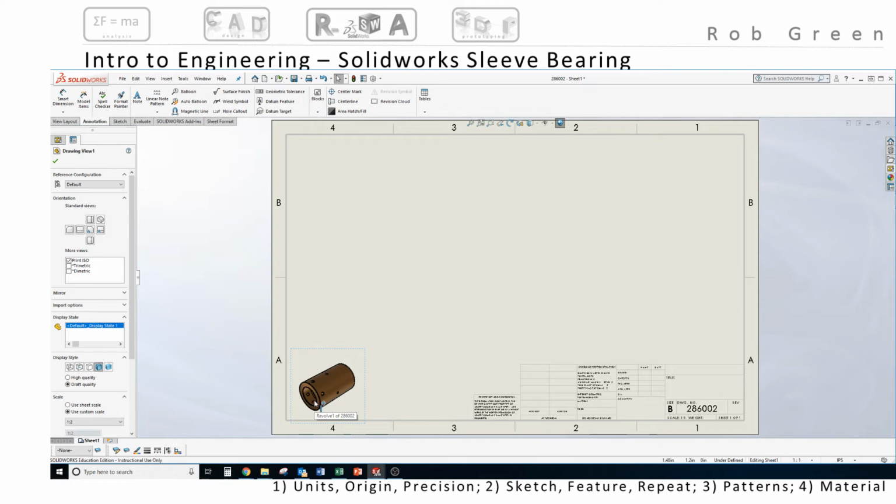manufacturing somewhere. In general, for a drawing layout, we're going to put our bill of materials, if we need one, in the upper left. In every drawing, we need a revision table, and that's going to go in the upper right. And any kind of notes that we have are going to go in the bottom right, and they are going to start at 1, proceed up to 2, up to 3, up to 4. So we want to proceed with our note numbers going up so that if additional notes are needed later, they can be added above without changing the entire organization of notes to add one more note at the bottom.